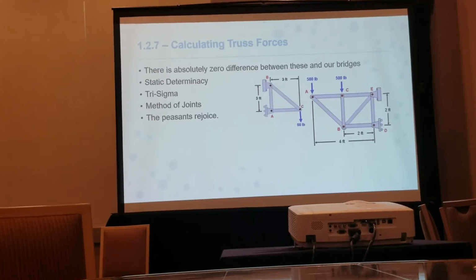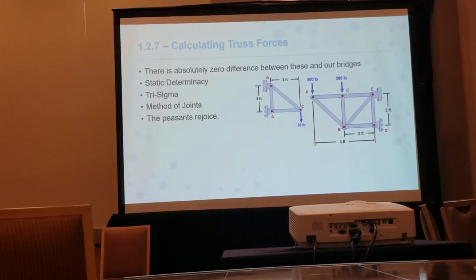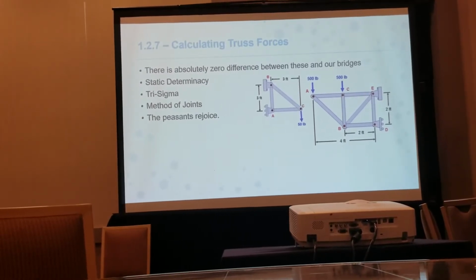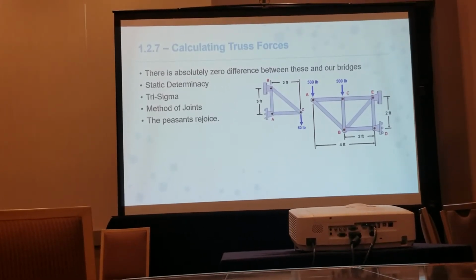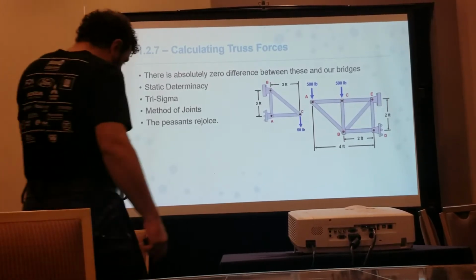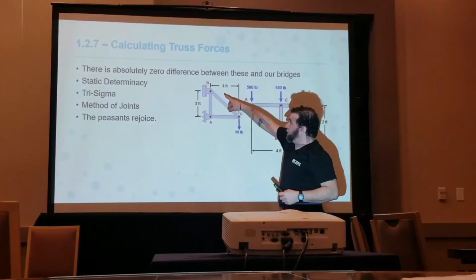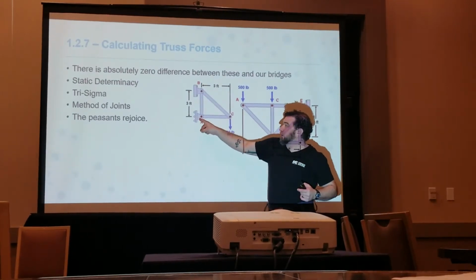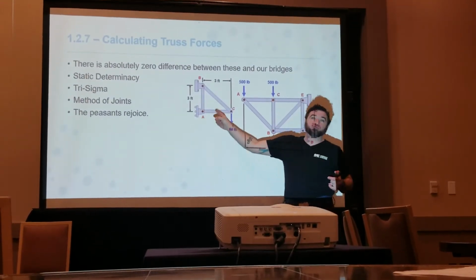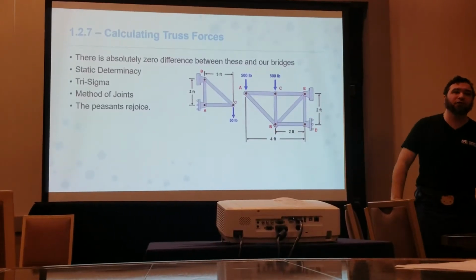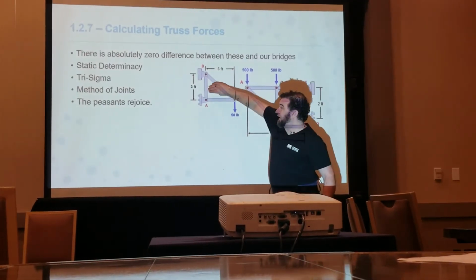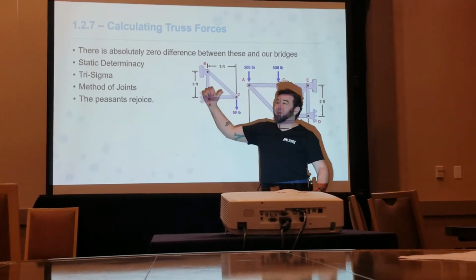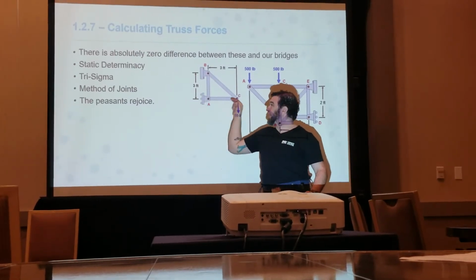I love it because now we get away from looking just at these simple truss bridges, and we start looking at these weird kind of, like this is what a sign would be. But again, we have a situation where we've got a pin, we've got a roller. This roller, what direction is that roller applying its force in? Y. X. Oh, it comes in now. This is allowing rolling up and down, so its force is actually in X, left and right in X.